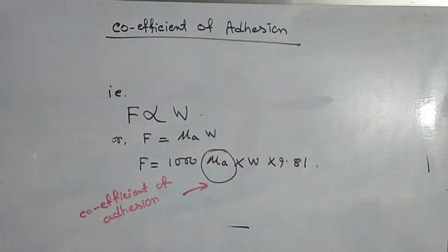This means the more uniform the tractive effort during starting and initial acceleration periods, the heavier will be the train which can be operated by a locomotive of given adhesion weight. This criterion is of paramount importance, especially in the case of goods trains, where the weight of the train usually approaches the maximum weight which can be handled by the locomotive.